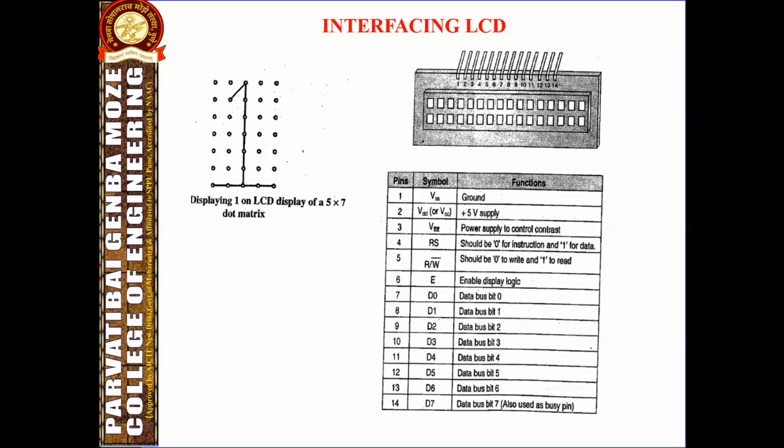So some commands should be given to control this LCD. We have to give some commands and codes to display particular things on the LCD, like force cursor to home position or blink cursor. There are multiple commands for clearing the display and returning the cursor, decrement cursor, increment cursor, shift the display right, shift the display left, display off.